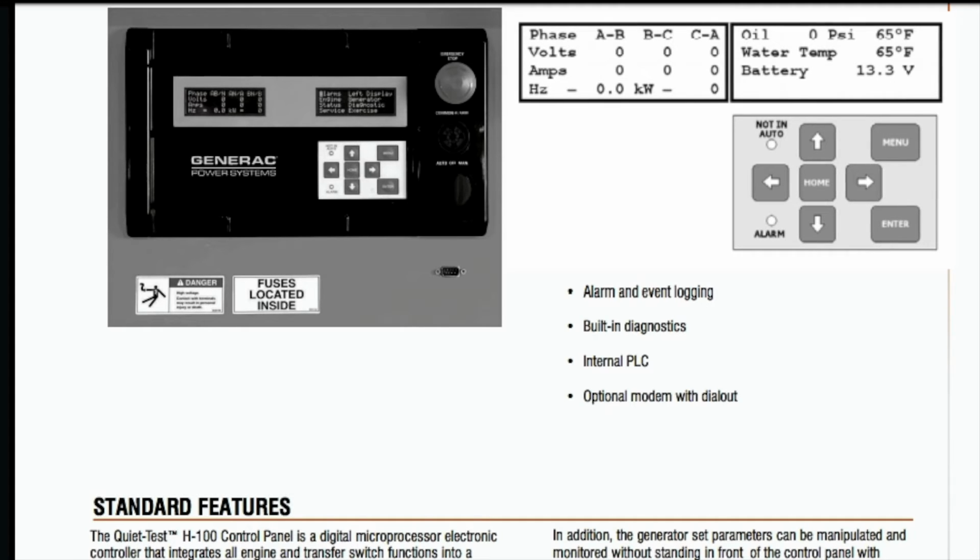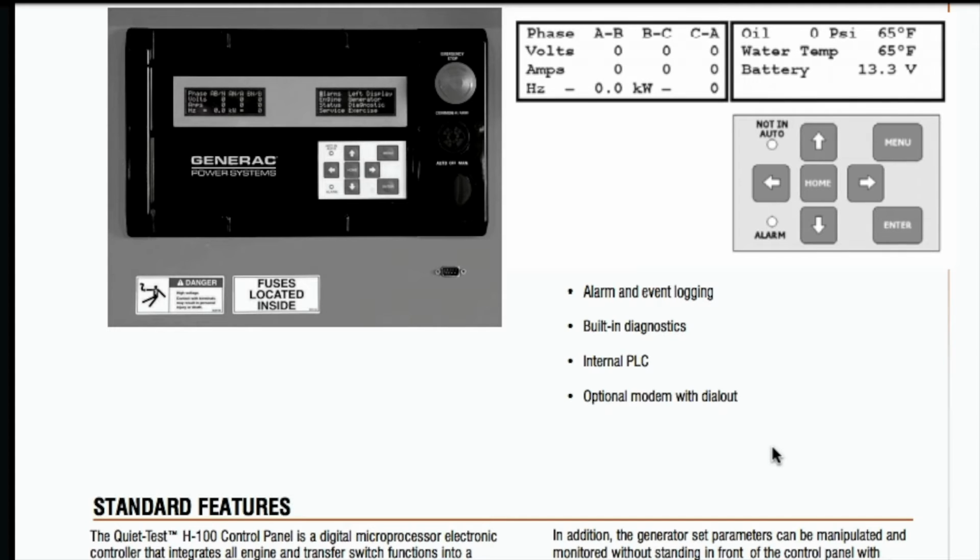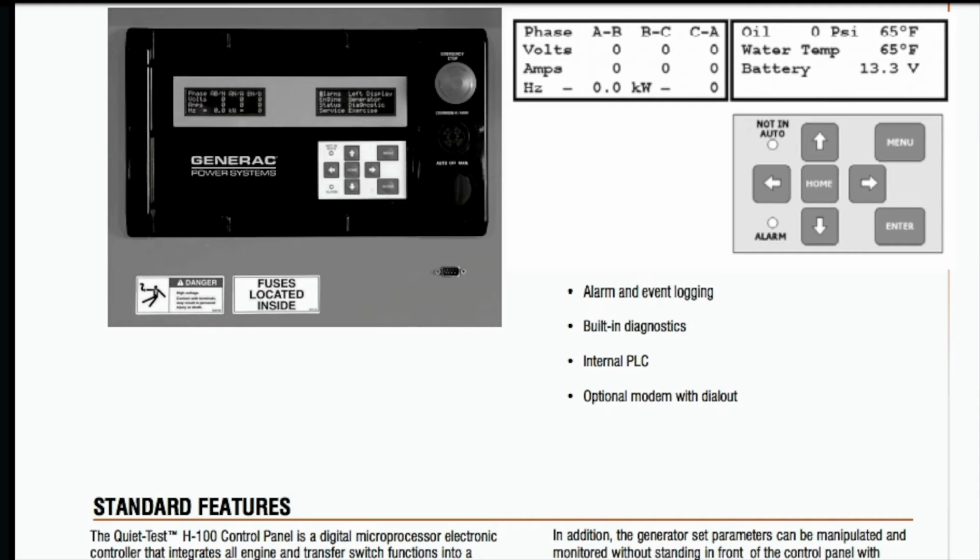Now, when you're not in edit mode, the arrow buttons are used to navigate around the page to either an edit field or a control field. And when you're in edit mode, the up-down buttons slew up or down through the available values, and the right and left buttons are used to change to a different digit or edit field. If you're moving off an edit field when in edit mode, it automatically enters the value displayed. Also, while in edit mode, pressing the home button will return the parameter to the last value entered.